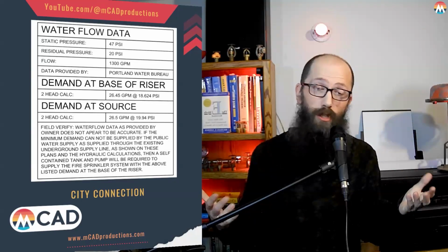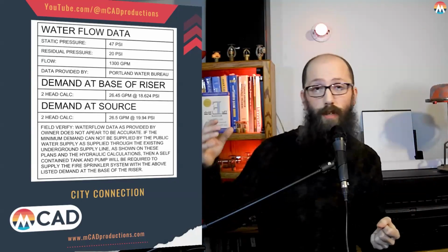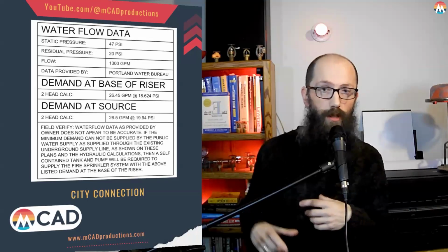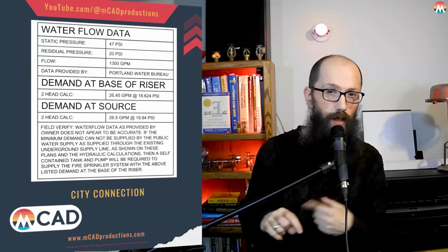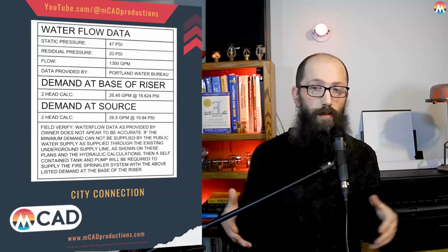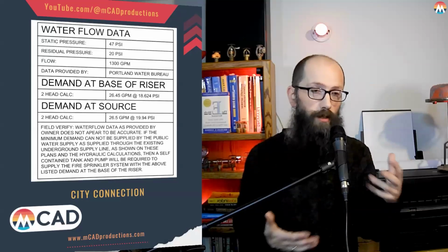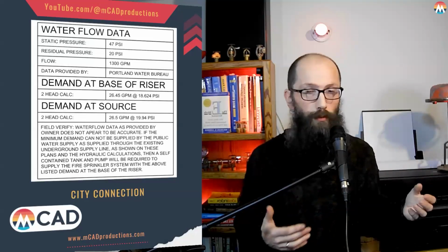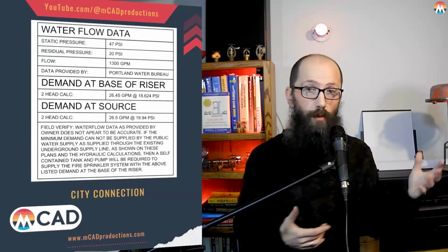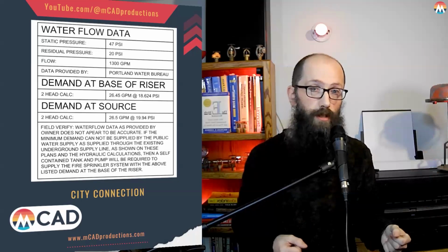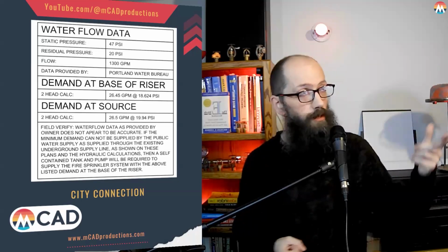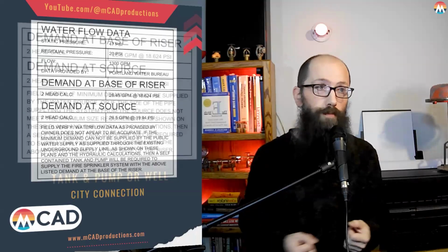The pipe could just be corroded because it's galvanized pipe, and so now it was 1-inch galvanized, but it's the equivalent of like 1/2 inch on the inside, so it just doesn't flow the way it calcs out because of the restriction in there. So basically, before it gets finalized, they will do a flow test and make sure that there is enough pressure. And if it doesn't work, they will have to switch to a tank and pump. That's what this disclaimer is here at the bottom.